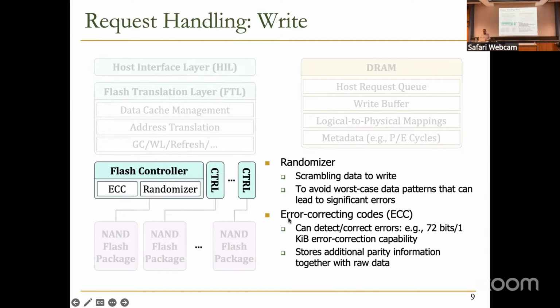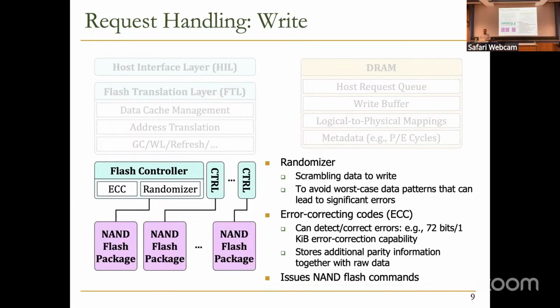And ECC, we talked about it, and we're going to see more about ECC when we do the read operation. After this part, the flash controller issues NAND flash commands, here the write command. It sends the write command, and after that sends the data burst, the amount of data that we want to write to the NAND flash package.